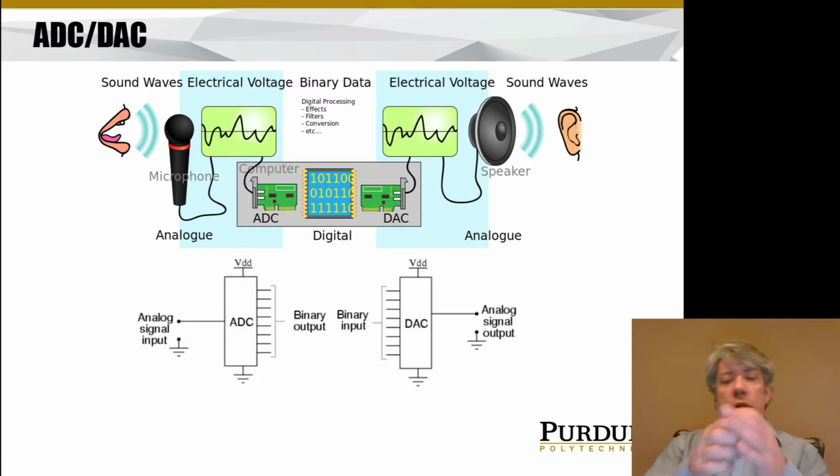Now what happens is there's a voice coil attached to that in a dynamic microphone, and there's other types of microphones that have a capacitor instead, but in a dynamic microphone it basically generates a voltage signal. So that motion is attached to a coil that moves in a magnetic field and generates a very small electrical voltage that can be detected by an analog to digital converter that's in your recording device, in my case my laptop that I'm recording this video on.